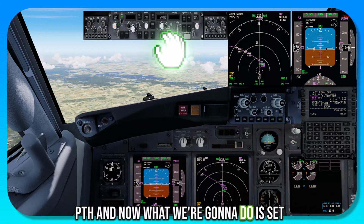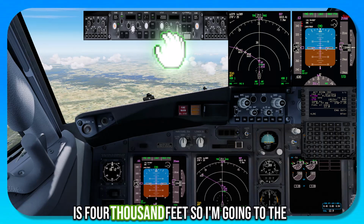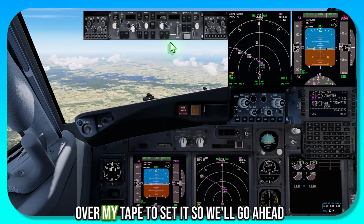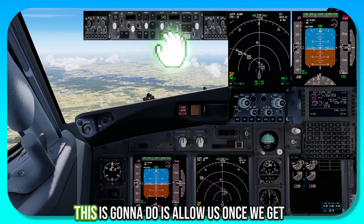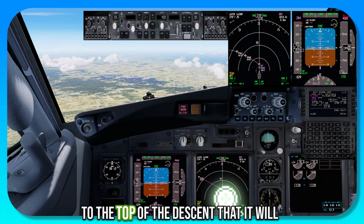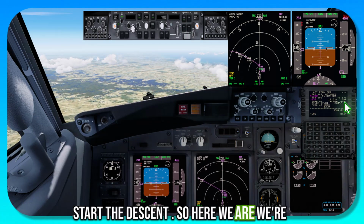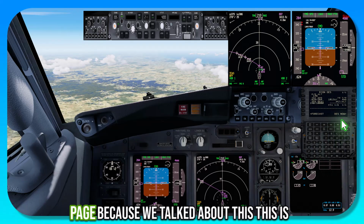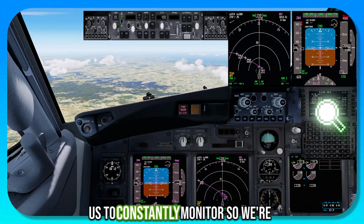And now what we're going to do is set the lowest altitude on this arrival, which is 4,000 feet. So I'm going to the altitude now, but I'm looking down here over my tape to set it. So we'll go ahead and set 4,000 feet. And what this is going to do is allow us, once we get to the top of descent, that it will start the descent. So here we are, we're 5 miles from this. Now what I'm going to do at this point is go over to the descent page, because we talked about this is going to be some valuable information for us to constantly monitor.